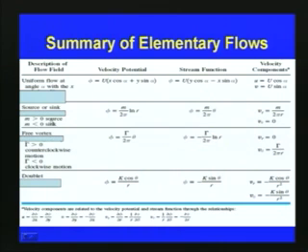And then we have seen the free vortex. For the free vortex, the velocity potential phi is equal to gamma, the circulation, by 2 pi into theta, and psi is equal to minus gamma by 2 pi natural log r, and the radial velocity v r is equal to 0, and v theta is equal to gamma by 2 pi r.